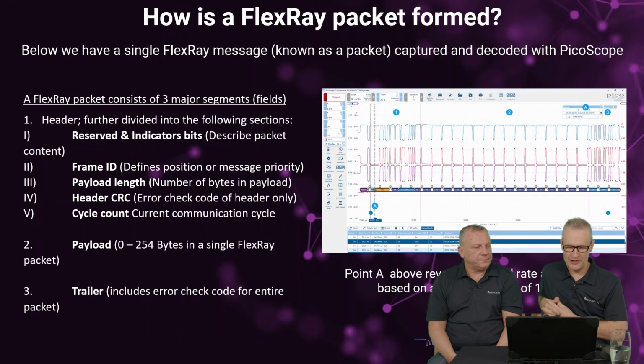That's something you mentioned earlier, was finding out who's on the network, and that was you would take a capture of data. If you've got a known good example, so you've got a vehicle, you've got a FlexRay capture, and then all of a sudden you've got a vehicle where an ECU or a node is offline. Take that capture, compare it with known good, look for the missing link. There'll be maybe an ID that is present on the good capture that's not there on your capture. Or ultimately use the export feature, which we'll come to.